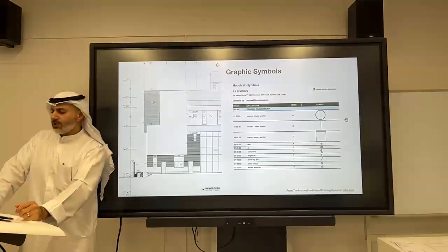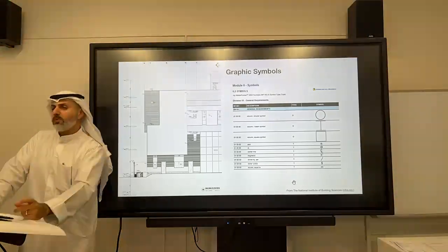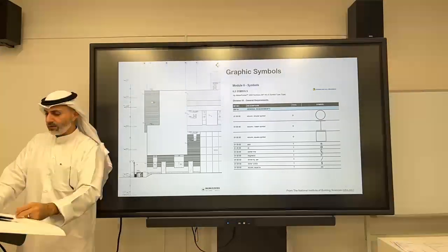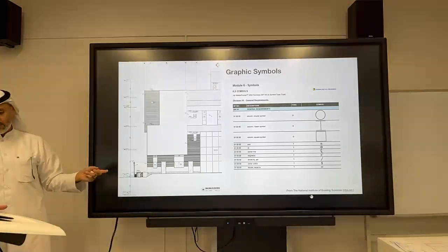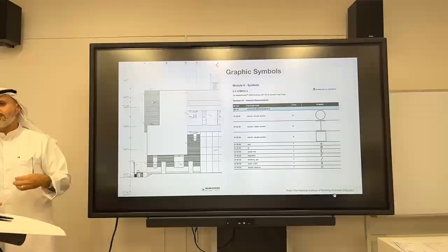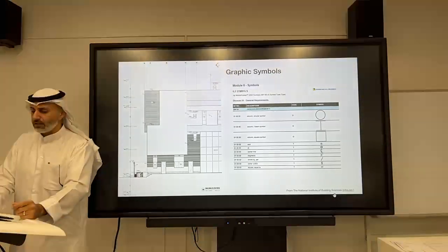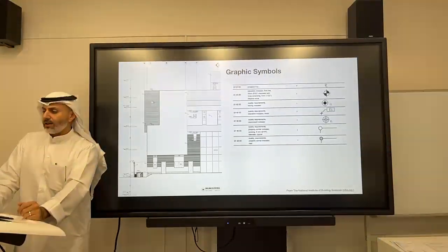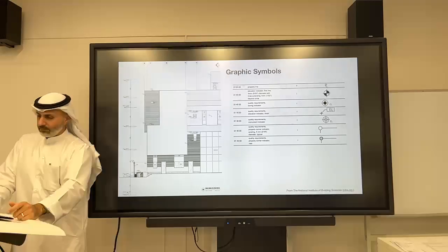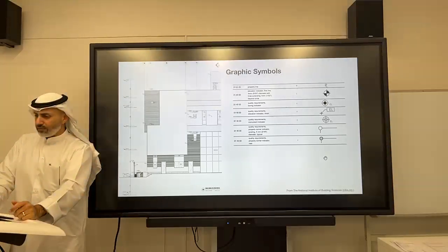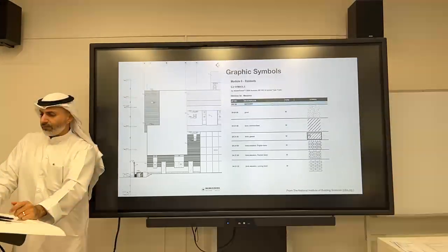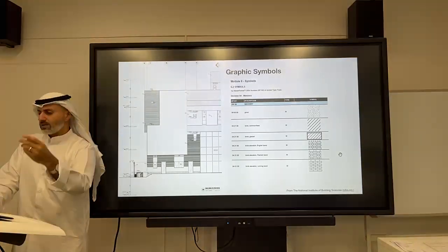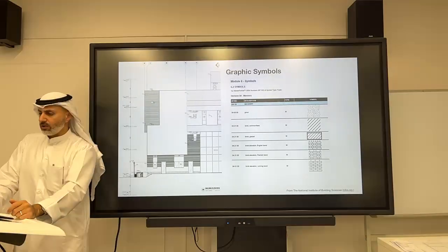I'm including a bunch of different symbols that we use both in elevation and plan, whether it's cut or seen in view. These are from the National Institute of Building Sciences that does standard symbols and graphics that are used in the field. So for example how to do a spot elevation, corner of the property, bricks, different materials, how to show them whether it's cut or seen in elevation.